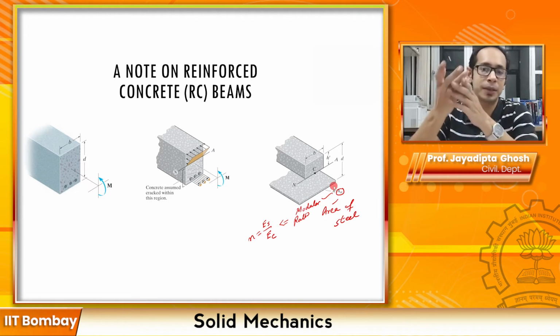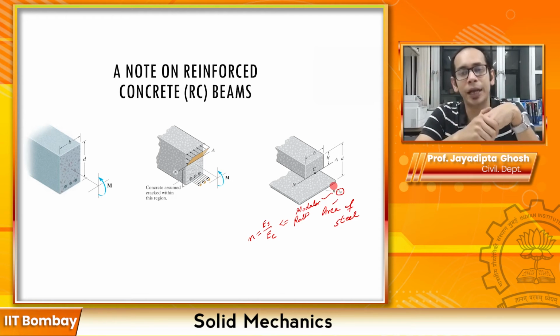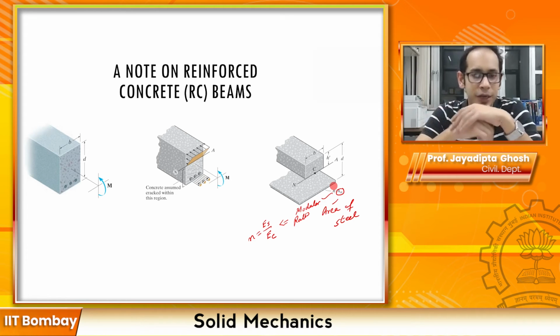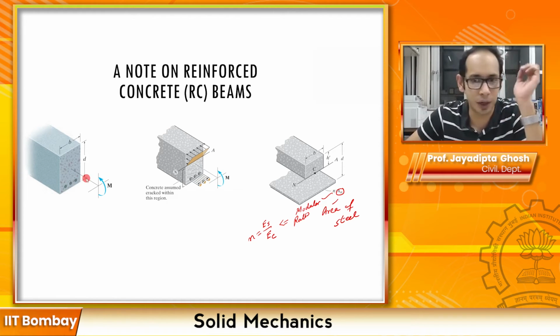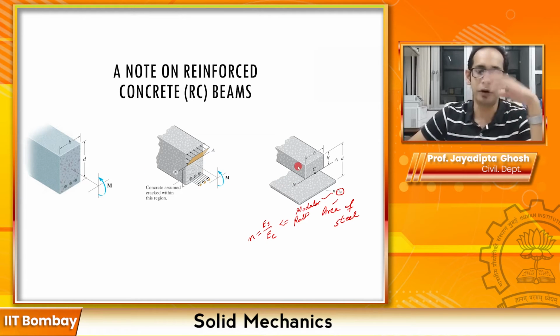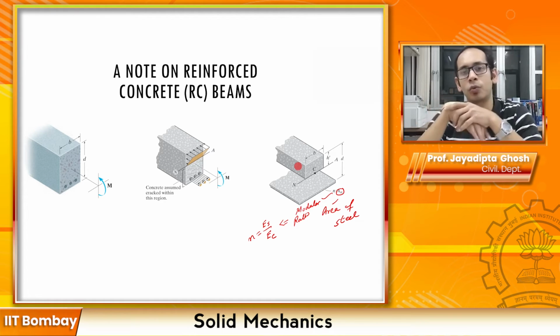Now this method of solving reinforced concrete beams and essentially designing, so see, the whole point of designing is that you're trying to find, to resist a particular tension, how much amount of steel do I need? Do I need 3 bars, 4 bars, or what is the grade of steel that you need, right? So this method of designing beams used to be a very integral part of what was previously known as the working stress method.